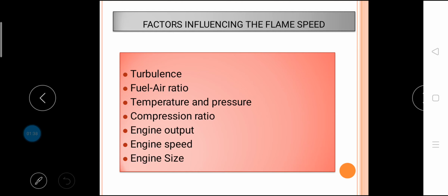The turbulence in the incoming mixture is generated during the admission of fuel air mixture through comparatively narrow sections of the intake pipe, valve openings, etc. in the suction stroke. Turbulence, which is supposed to consist of many minute swells, appears to increase the rate of reaction and produce a higher flame speed than that made up of larger and fewer swells. A suitable design of the combustion chamber, which involves the geometry of cylinder head and piston crown, increases the turbulence during the compression stroke. Generally, turbulence increases the heat flow to the cylinder wall.